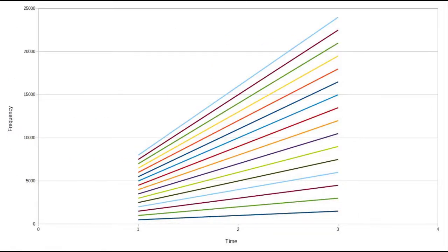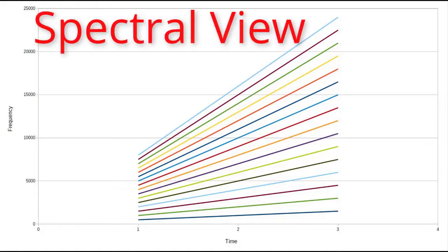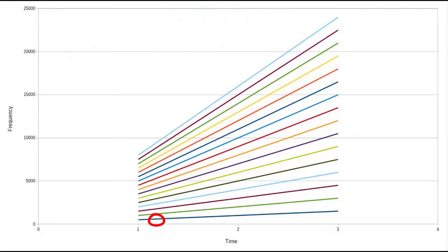There is also a maximum base frequency we can use a wavetable for. Here we have a wavetable containing 16 harmonics. We are using it to generate a sawtooth wave starting at a base frequency of 500 Hz and increasing the frequency to 1500 Hz. At 1500 Hz, the frequency of the highest harmonic has reached the Nyquist frequency at 24 kHz. If we try to use this wavetable to generate a sawtooth wave of a higher frequency than this, the harmonics will exceed the Nyquist frequency and we will be introducing digital noise.